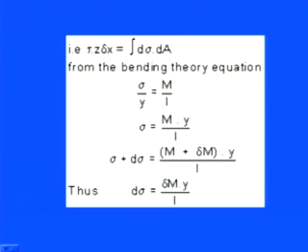So here we have the shear stress tau into z into delta x equals the integration of d sigma into dA, and we have the other stress formula, d sigma, which is nothing but delta M into y divided by I. If you compare both equations, you will find that these stresses are the resultant stresses coming due to the shear forces, that is tau, and due to the bending moment, delta M. That means whatever normal and shear stresses are coming are the resultant of these two portions.